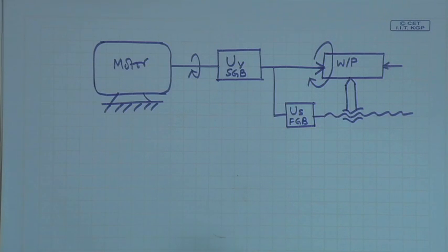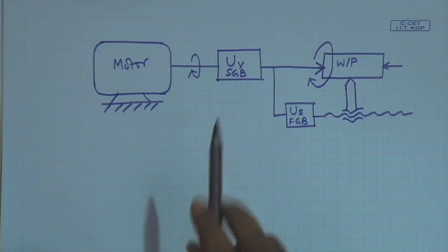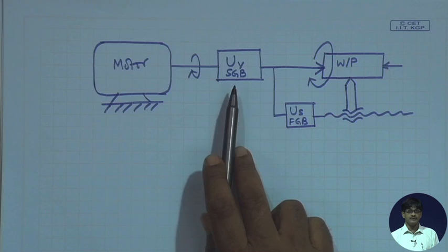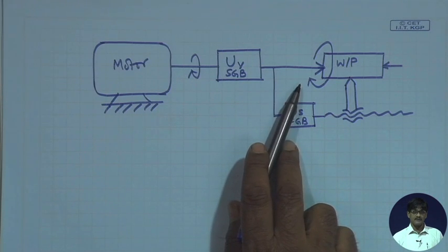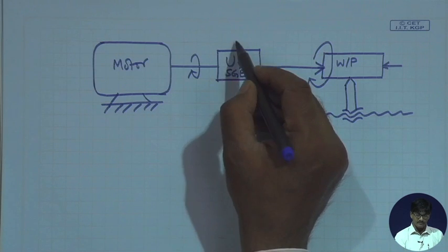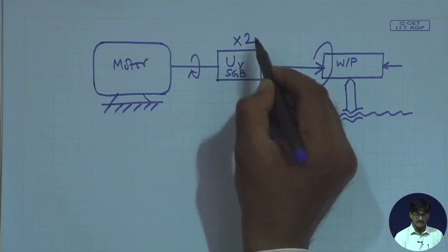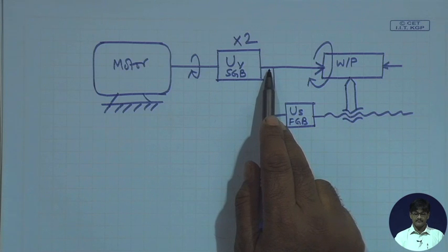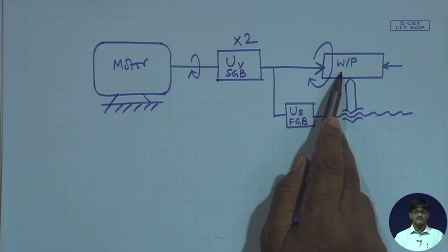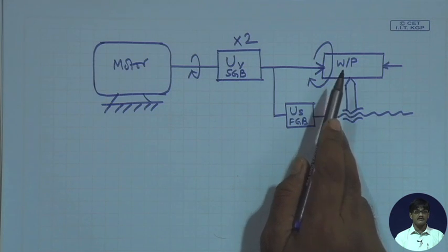This was the figure in case of the lathe. The same thing was happening. UV is placed ahead of everything, and therefore, if UV is doubled, suppose I make a setting of the UV so that the output RPM is doubled. In that case, the rotation of the workpiece doubles and the cutting speed is made double, exactly what we wanted.